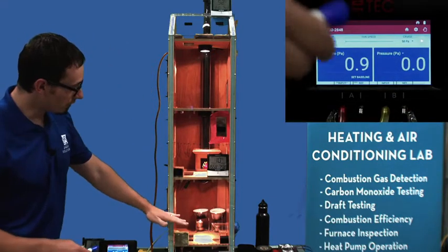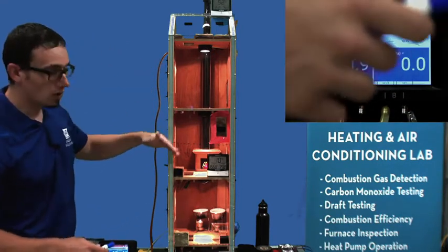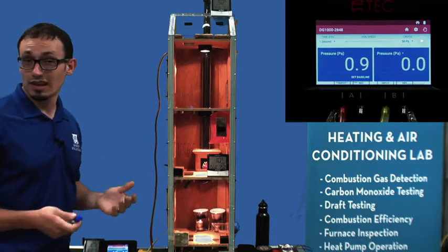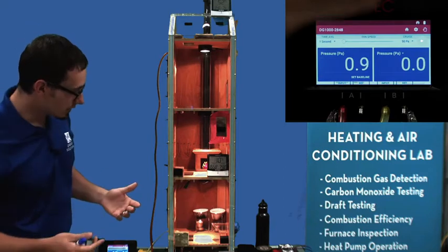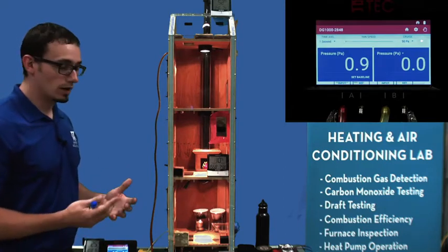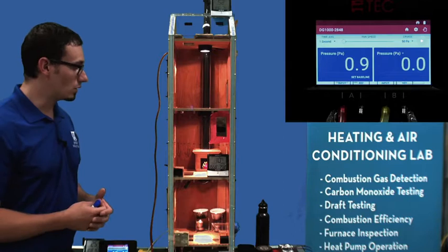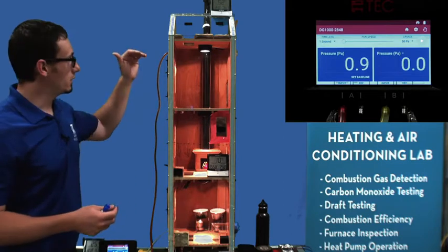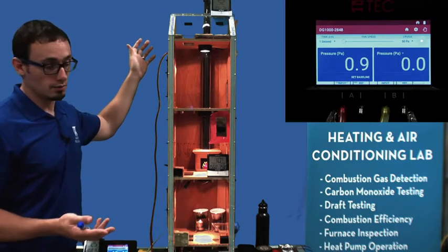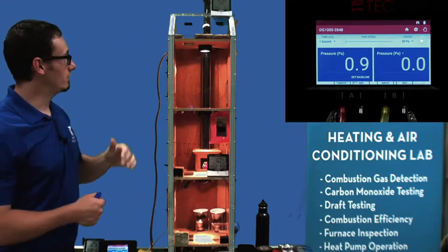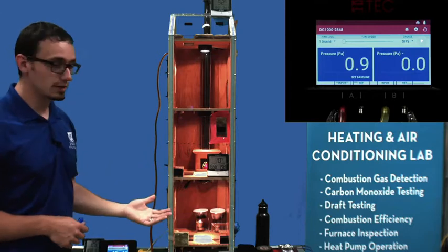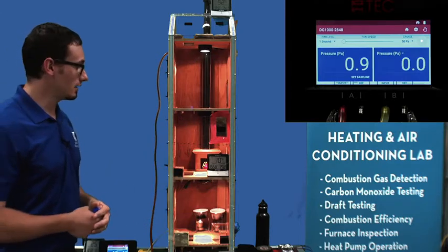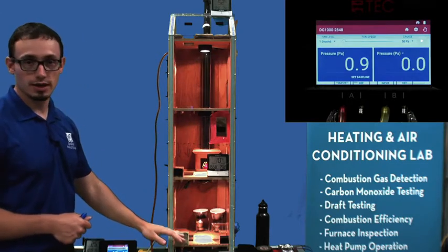So now everywhere along this wall is going to be a positive pressure, slightly positive relative to the outside. And ideally, in terms of indoor air quality and control, that's what I want to have: a building that's sealed at the top, well, top and bottom, but especially first at the top, to create this effect in controlling that stack effect and moving that neutral pressure plane down.